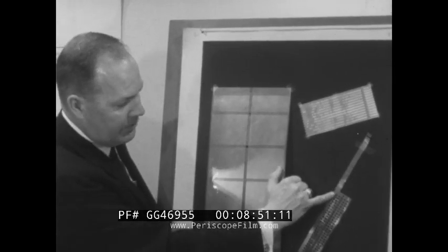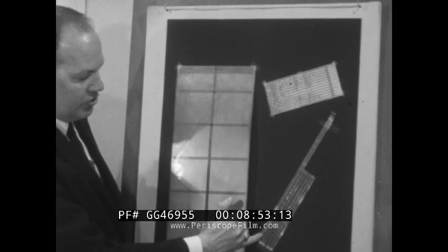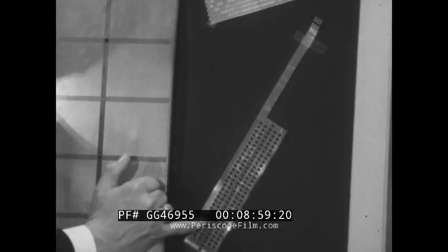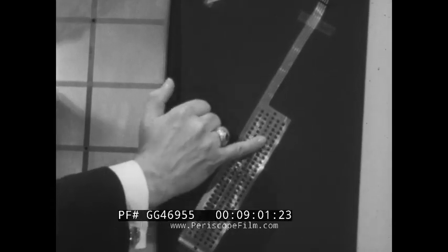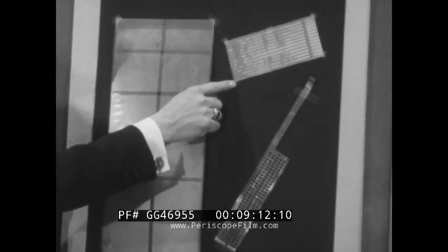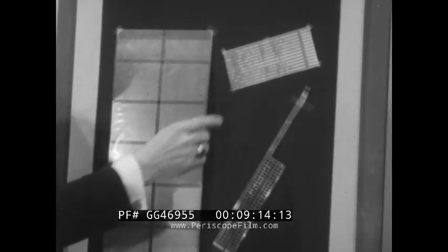In the case of the Model 40, a microinstruction word is comprised of 60-bit positions. The outside row forms one word, the inside row forms another word. So each of the tapes in a Model 40 has 2 microwords. Each of the cards in a Model 30 has 12 microwords.